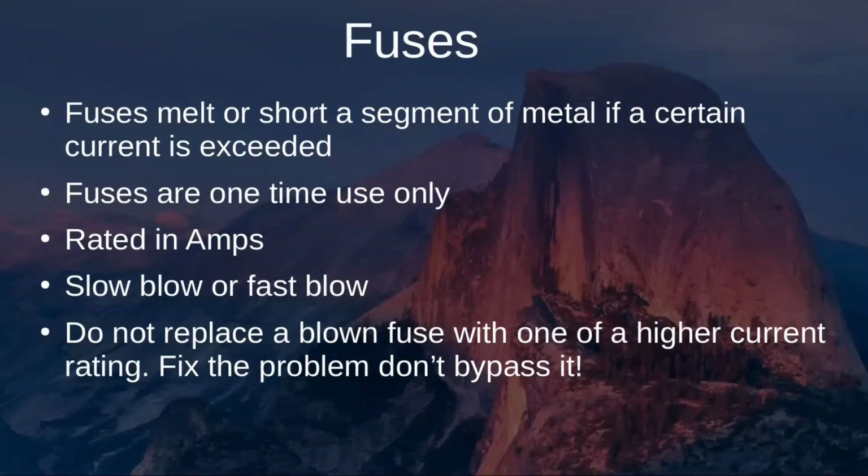Another important thing to remember is that if a circuit breaker or fuse blows and you need to replace it, find out what the problem is. That circuit breaker or fuse activated for whatever reason, because there was a short circuit or an excess of current draw within the circuit, and you need to find the problem before you replace it with another fuse. And never, ever, ever replace a fuse with a higher value. So if the fuse is rated for 10 amps and it blows, don't put a 20 amp fuse in the circuit. You're just bypassing the problem and asking for trouble.